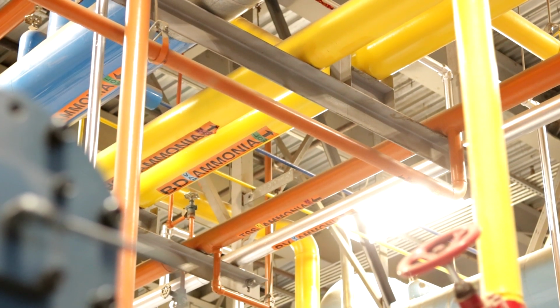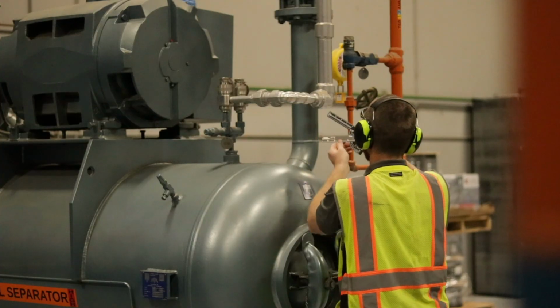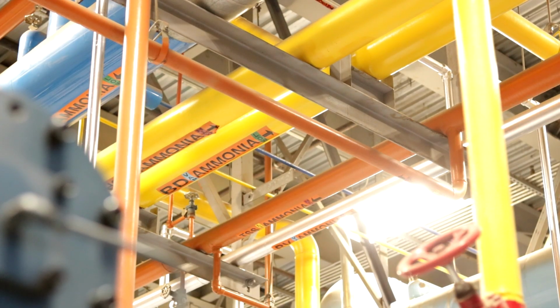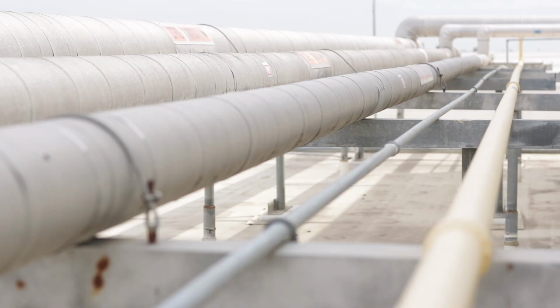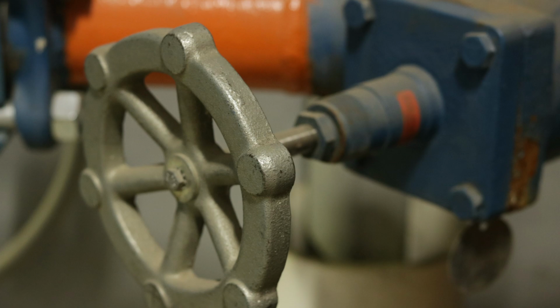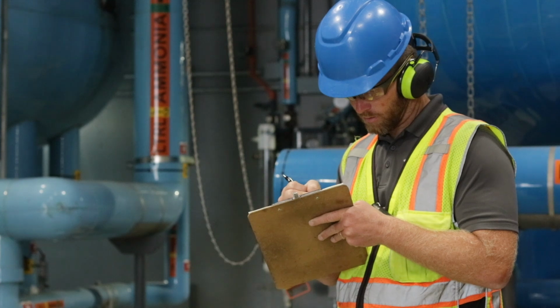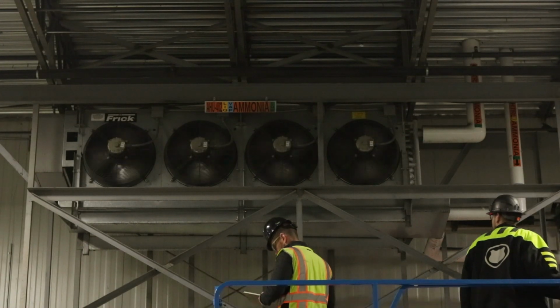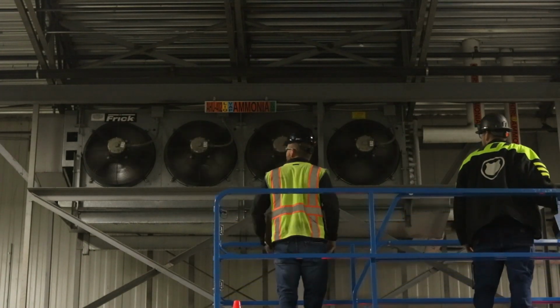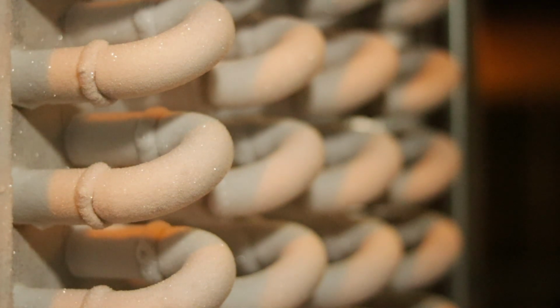Many factors contribute to pressure differences in a system. First, the diameter of the pipe. The larger the diameter, the less pressure drop there will be. Second, the length of the pipe. The longer the pipe length, the greater the pressure drop will be. Third, pipe fittings and valves. Whenever a fluid flows through a valve or around a 90, there are pressure losses as fluid changes direction. This results in a pressure drop. Finally, the velocity of fluid flow will affect the pressure drop. The faster the fluid is flowing, the greater the pressure drop will be.